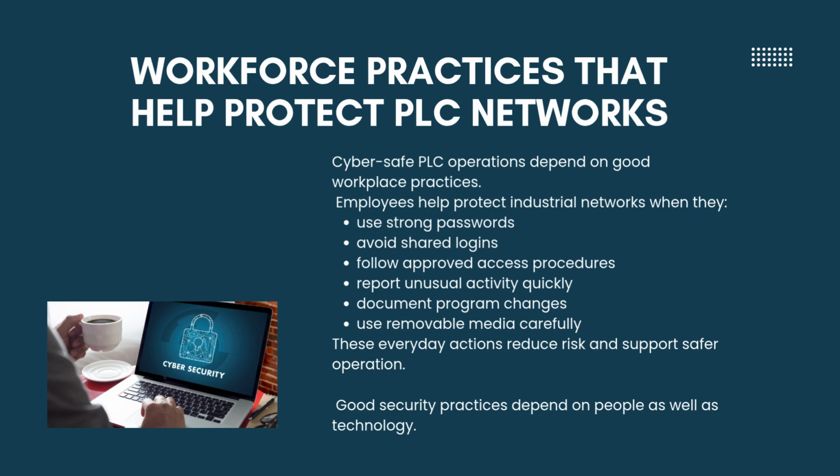Workplace habits matter too. Cybersafe PLC operations depend on good workplace practices. Employees help protect industrial networks by using strong passwords, avoiding shared logins, following approved access procedures, reporting unusual activity promptly, documenting program changes, and using removable media carefully. These everyday actions reduce risk and support safer operation. Good security practices depend on people as well as technology.